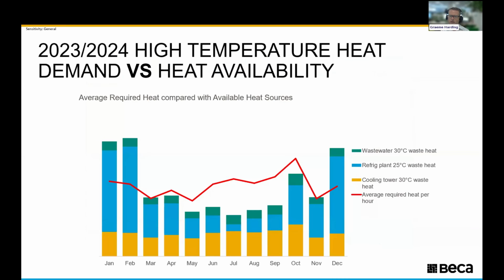And the only thing that we had to be aware of that caught us a little bit on that job was we needed at least 2 high-side compressors to run all the time to provide enough ammonia. And we did notice that when the heat pumps were running in the evening, we dropped the discharge pressure, and so the hot gas defrost didn't work so well. And so we had to move the hot gas defrost time, and then everyone was happy after that, and it's performed very well.